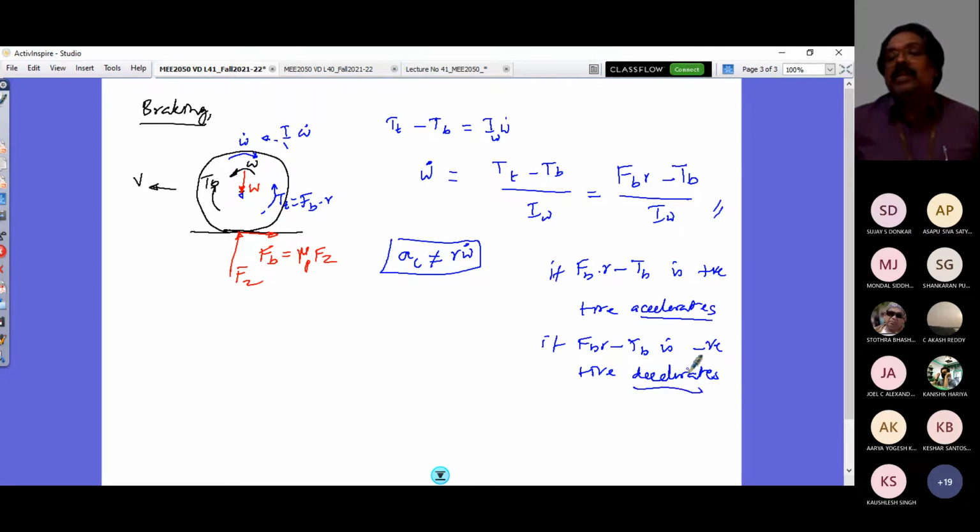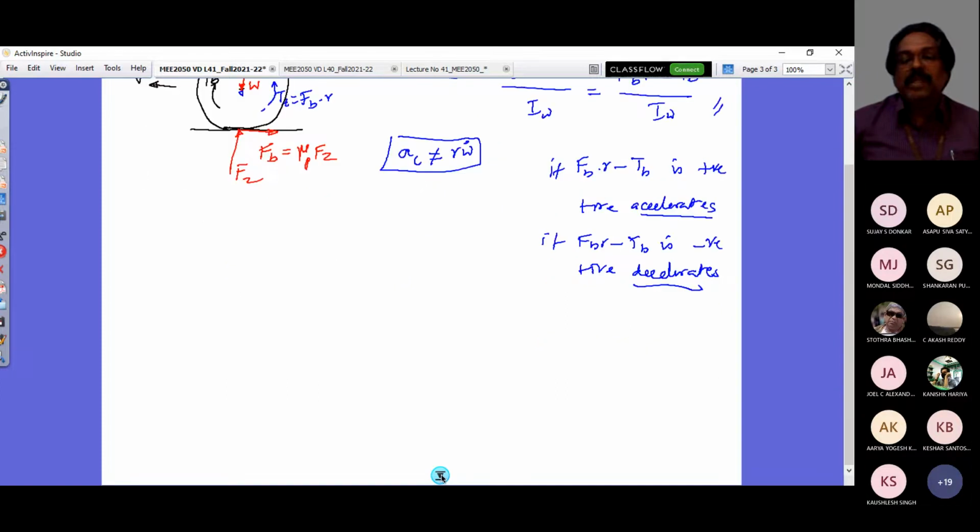In ABS, the brake action is not only to decelerate your wheel. Within a millisecond duration, your wheel would accelerate and decelerate. It will be reducing the speed, then it will stop reducing the speed, then it will be increasing the wheel speed, then again decreasing. So it is gradually going to take the omega of this wheel to 0. That's what you are going to witness now, and how that is working. If you look at the ABS in your vehicle, it is an electronic feedback control system.